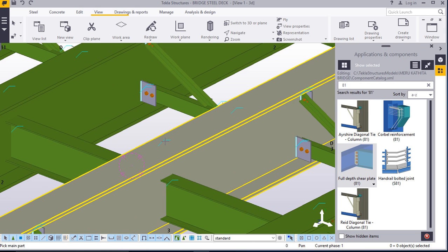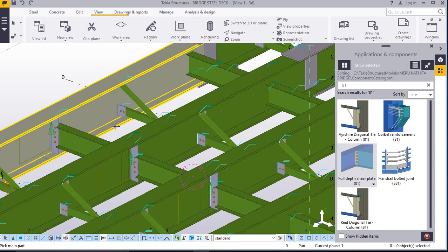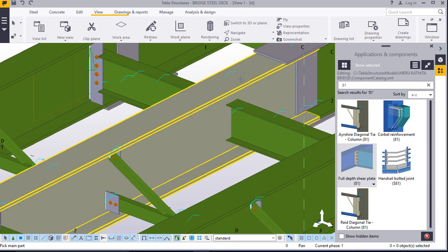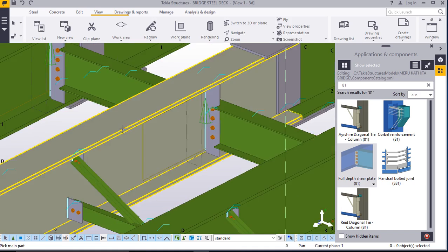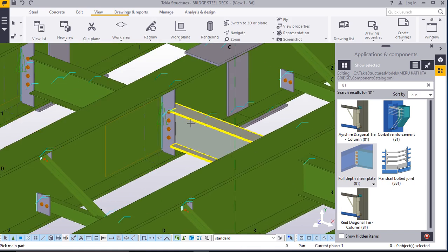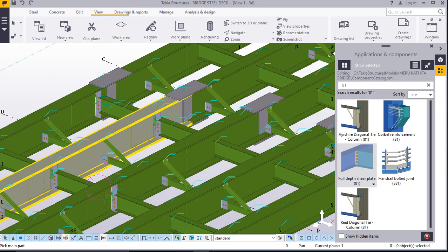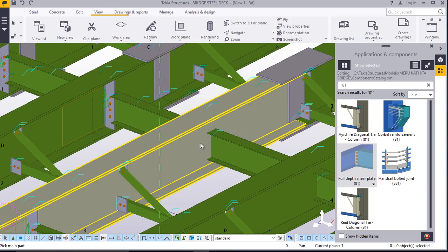Click this main member and that and this and that, this and that. Just move on that first, because Tekla will just remember the settings you enter on the first joint. It will use all the settings for all the joints of the same setting. Click that and here